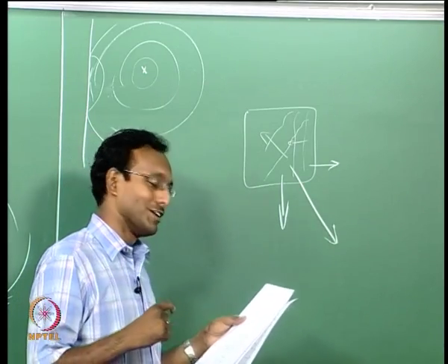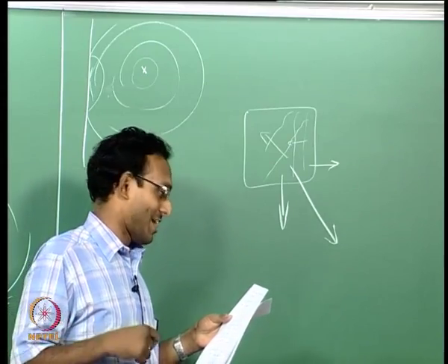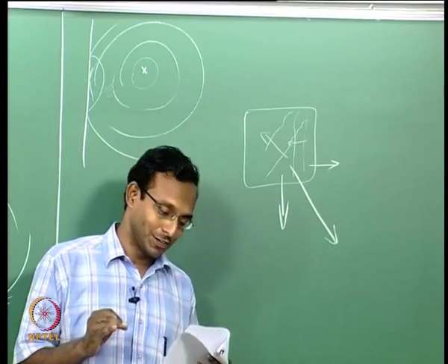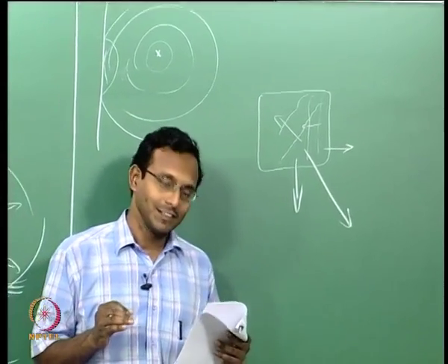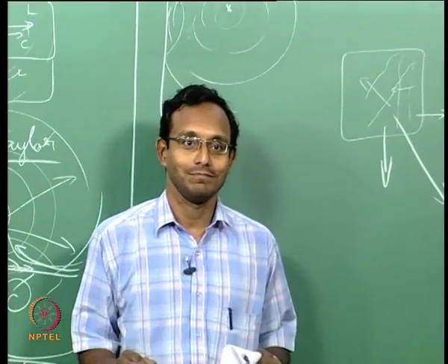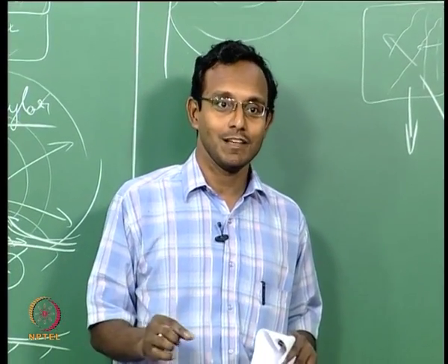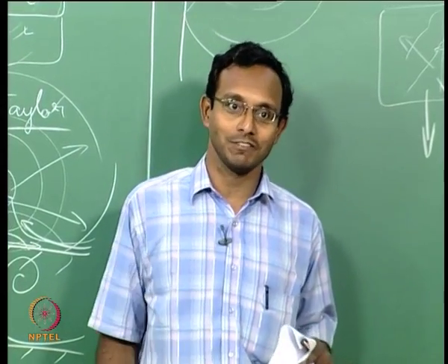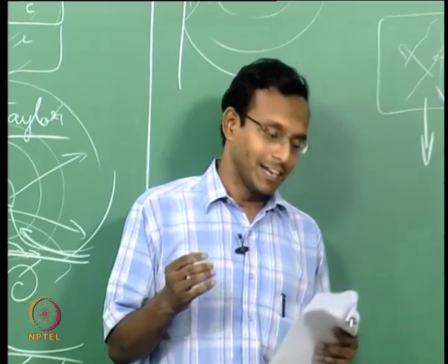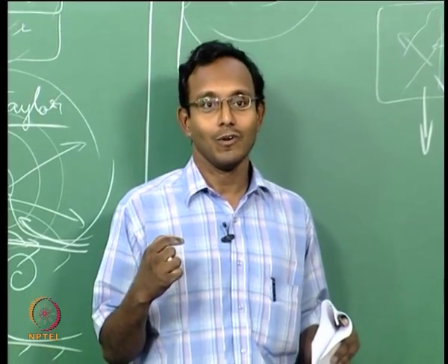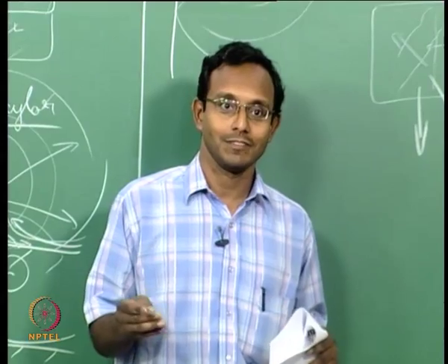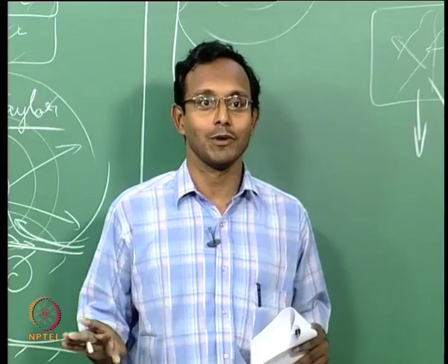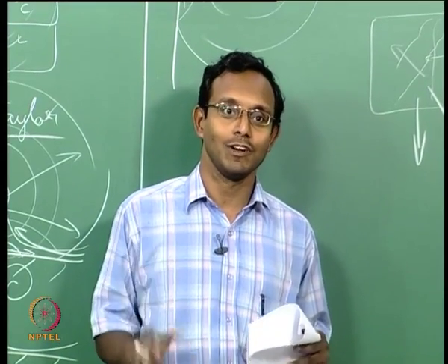So now I will put more strong statements after all this. I am going to say the only way to change the pressure of a gas is by a compression wave. I cannot change the pressure of a gas by any other means. I can increase the pressure of a gas only by sending a compression wave. I can decrease the pressure of a gas only by sending an expansion wave. Okay, increase pressure by compression wave, decrease pressure by expansion wave. There is no other process by which I can change the pressure of a fluid element.